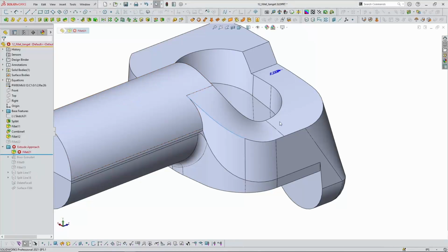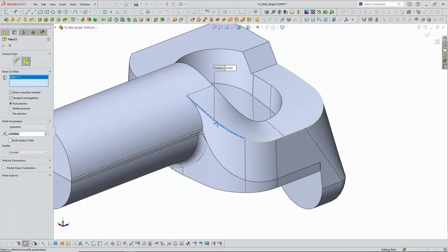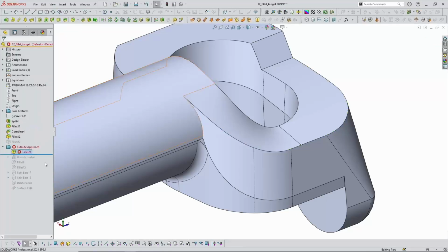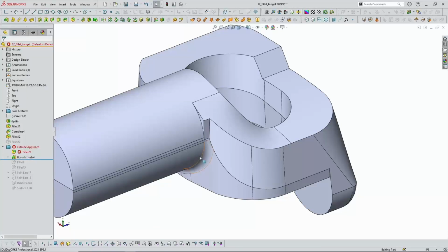So I was going to try to add another 1/4 inch fillet to this top edge, but this surface was manually created with a surface blend. The software probably doesn't know how to extend this intersection as this fillet kind of fades out to nothing in this instance. And so to work around that, I've added a little bit of material to the model, and now I have this nice new face that I can stop my fillet at. Now this fillet has no problem terminating.